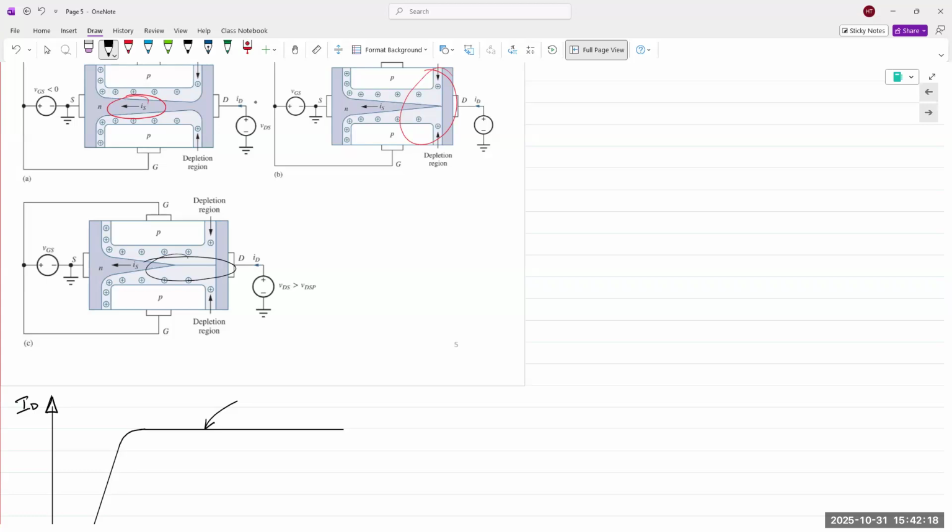So the only difference between a voltage source and a current source is the mode of operation. If it can supply a constant voltage, it's a voltage source. If it can supply a constant current, it's a current source. So any benchtop supplies that we have in our lab benches are both a voltage source as well as a current source. There's a tiny CV or a CC somewhere on the front panel. That's all it means.